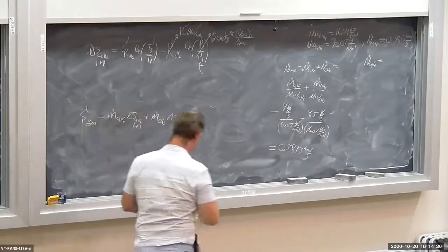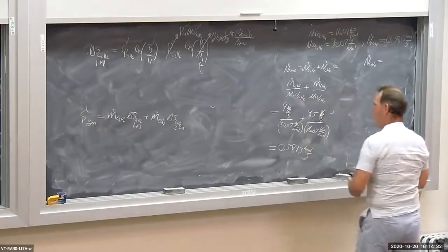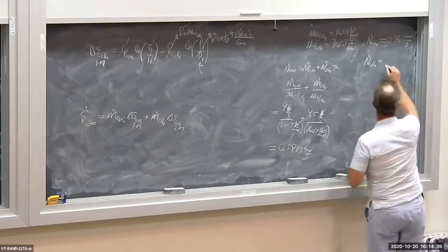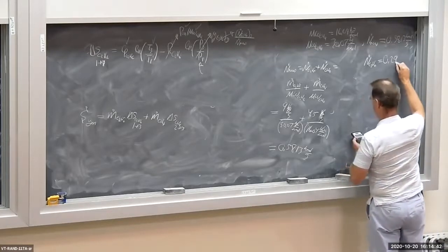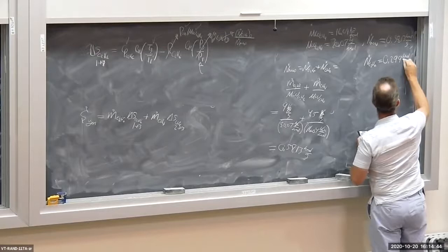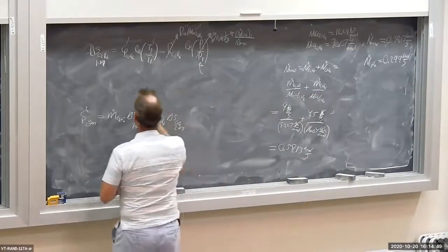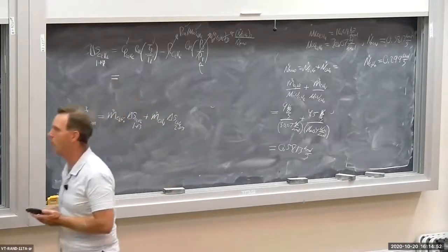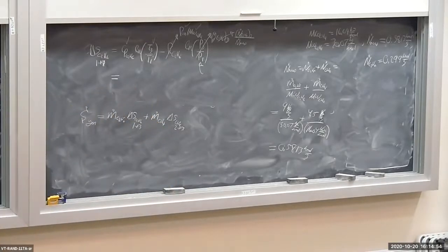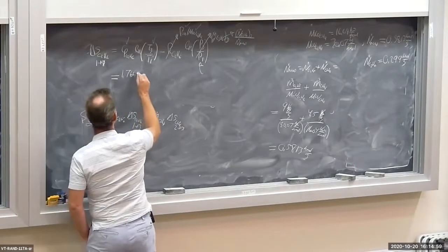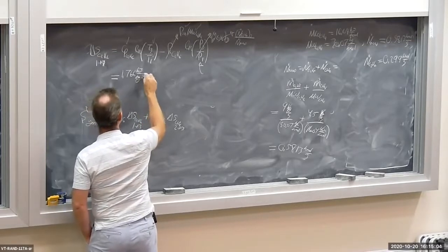Well, that's going to be here. This is for the ethane, so 9 divided by 30.07. And I get 0.299 kilomoles per second, okay? Okay, so let's plug in specific heat for the ethane, 1.766 kilojoule per kilogram degree Kelvin.